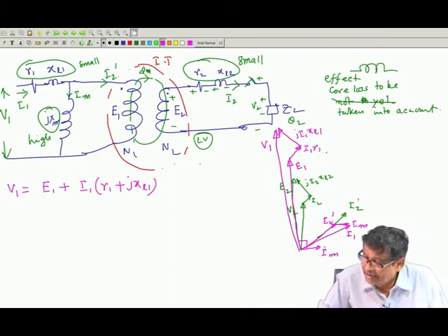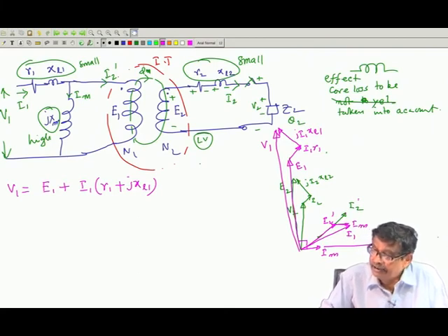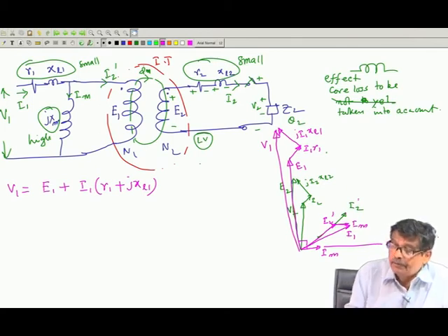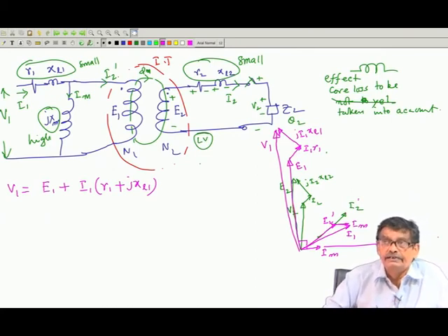This will be the, and here is the flux along this line. I think you have got the idea. It looks like, oh, it is quite involved. No, not really. We will see later how things will become much easier. With a few approximations here and there, things can be further simplified. So, what I told you is that it is almost a practical transformer, except core loss is yet to be taken into account, where I have considered the winding resistances R1 R2, where I have considered the finite magnetizing current, and the effects of this are easily seen.